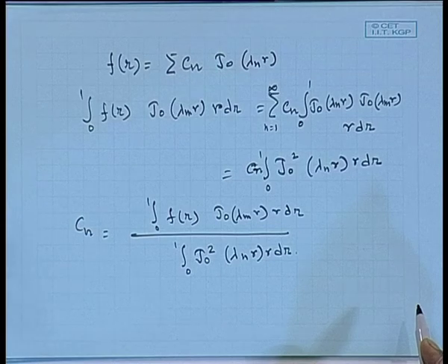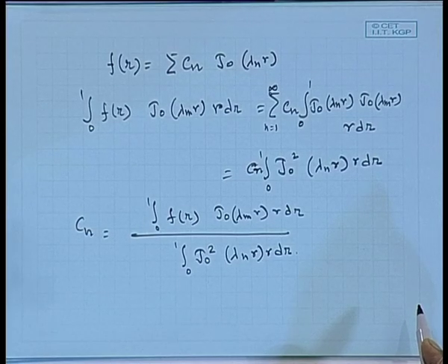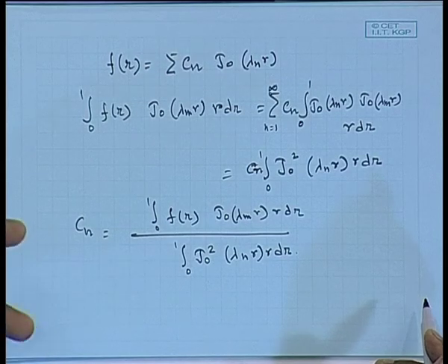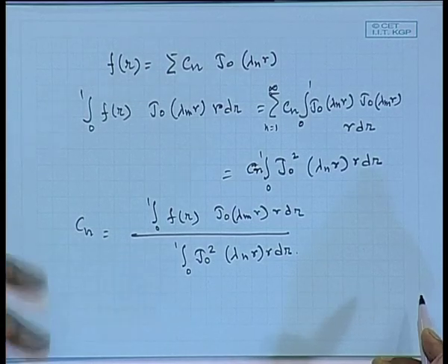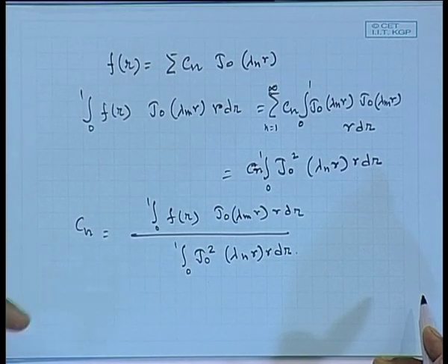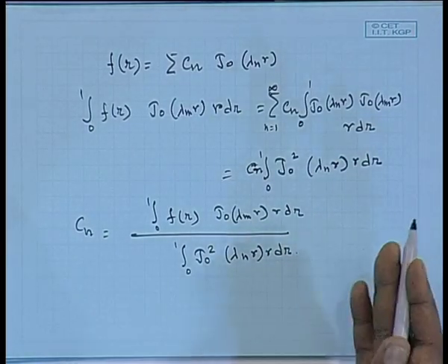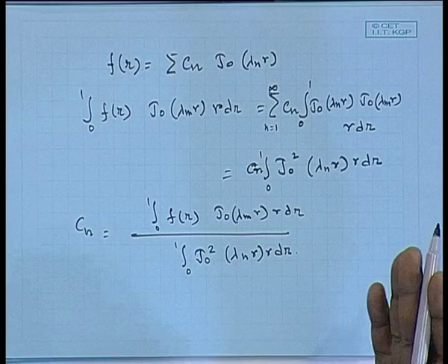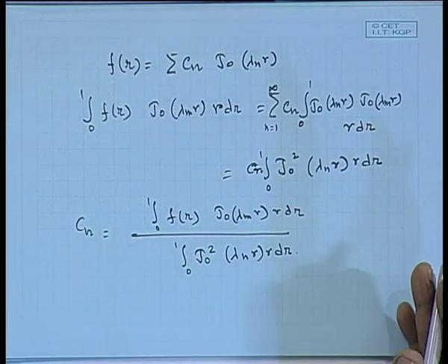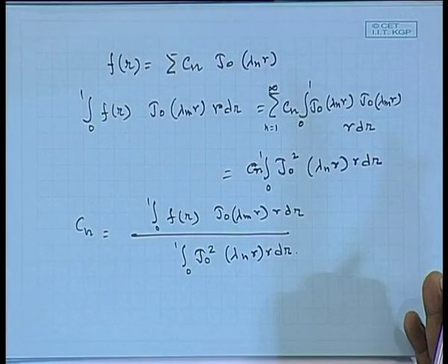But whenever you will be evaluating the temperature as a function of r and t, you cannot do it analytically like the sine functions or cosine functions, because the complex forms of the Bessel functions are all infinite summation series. So, all these calculations have to be done numerically, meaning evaluations of Bessel functions will be done numerically. The compact form of the solution is available in front of you, which is almost equivalent to an analytical solution.